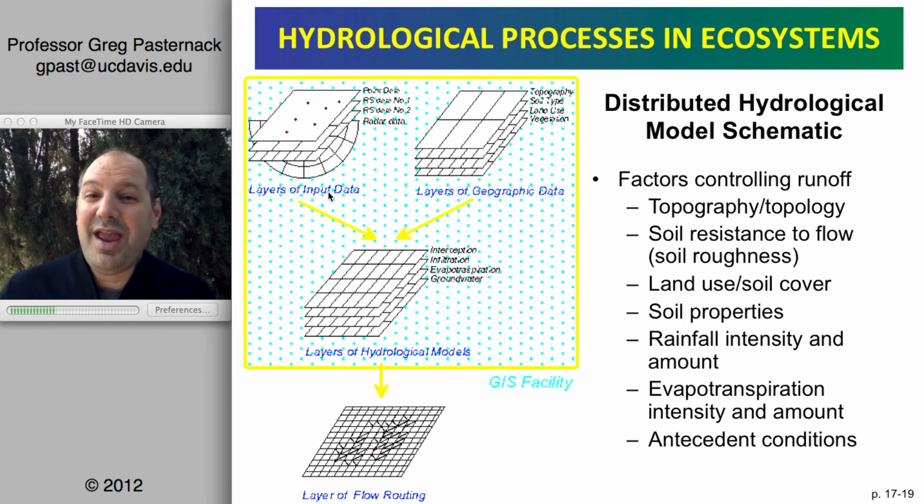So that means rainfall. Well, that's the main input, but you might also have stream flow or groundwater flow, I guess. So you're going to have a spatially distributed map of that. And of course, we often don't. We often have 1, 2, or 3 gauges if we're lucky. So you have to have a way of taking the data from that gauge and distributing it across the landscape.